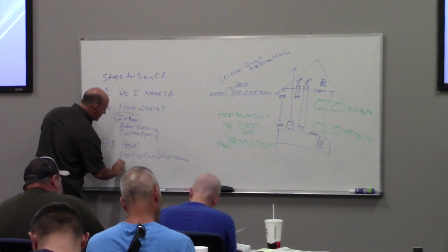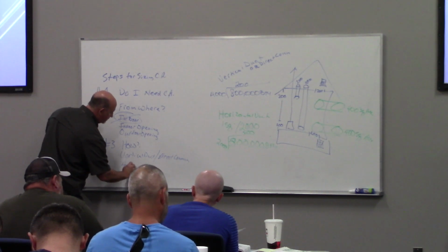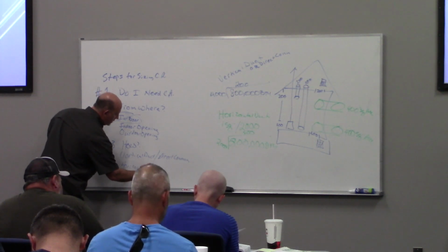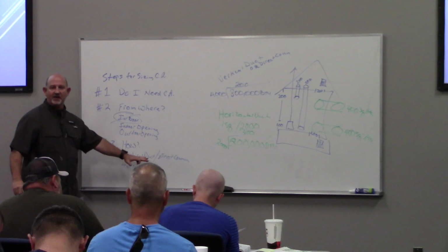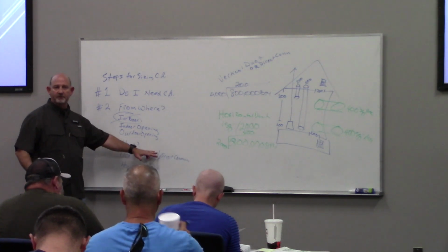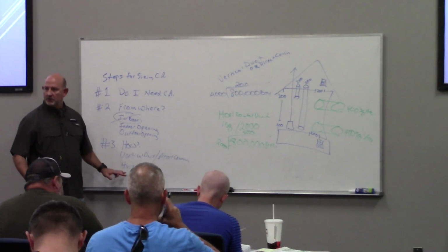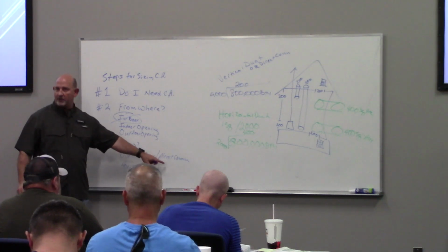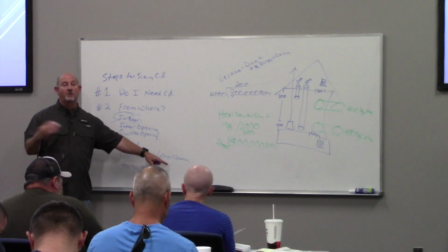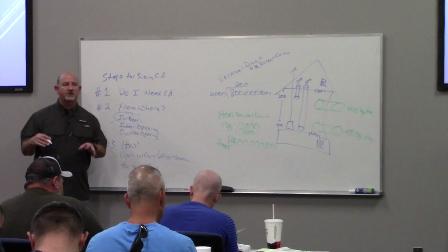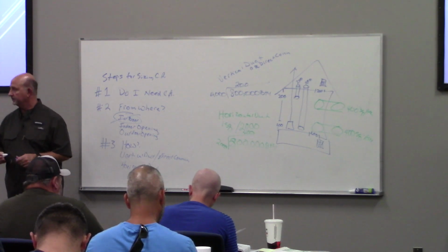Or am I a horizontal duct? Now again, you notice I put those 2 on the same line because that's both number 1 and this is number 2. Whether you're a vertical duct or directly communicating with the outdoors, that's 701.6.1 number 1. Horizontal duct, 701.6.1 number 2.